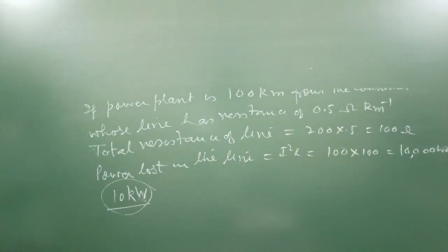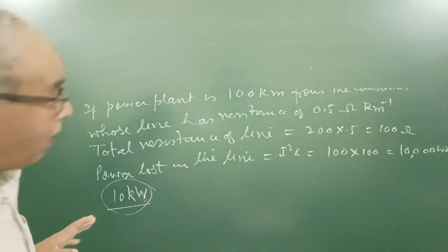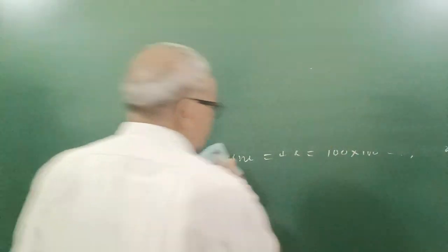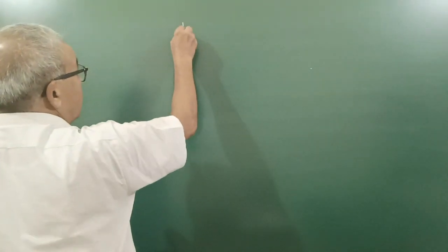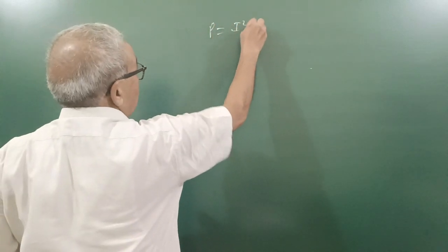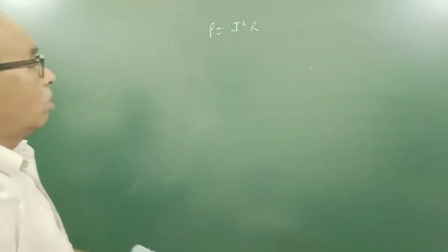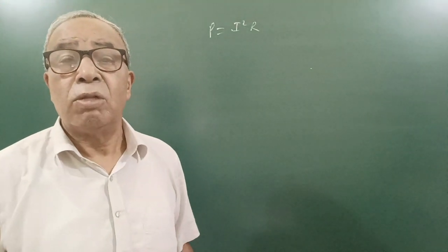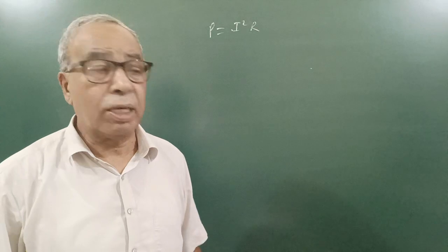electricity is transferred through conducting wires. So the conducting wire has resistance, so power loss is certainly there. So how to minimize? Power produced as heat is I square R. Two factors are there. Either you decrease resistance, so you need thick wires of conductor.